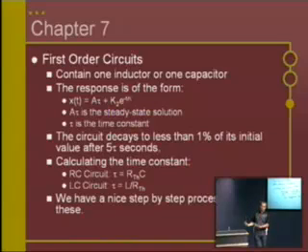It doesn't. It acts like a short circuit. But just make sure that you keep that straight. So then you zero out all the sources, find the Thevenin resistance, and then either multiply that by the capacitance or divide the inductance by the resistor to find out what the time constant is. Solve for the constants K1 and K2, and you will have the circuit.